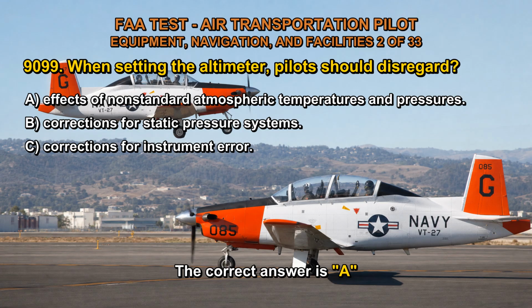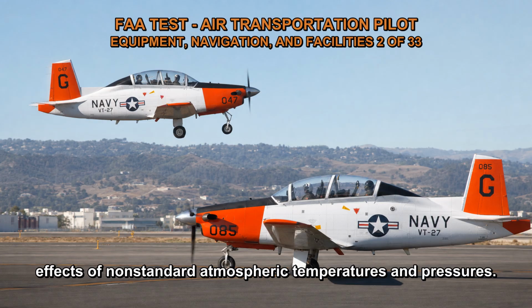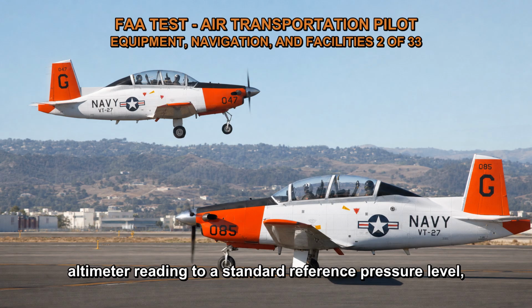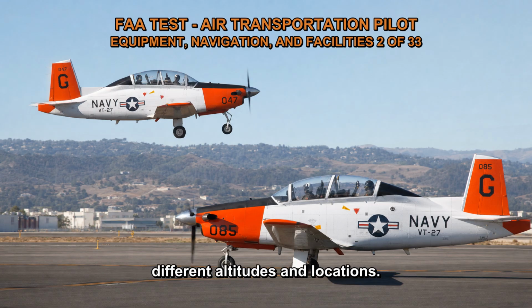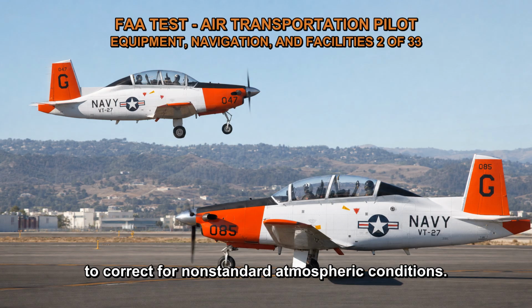The correct answer is A. When setting the altimeter, pilots should disregard the effects of non-standard atmospheric temperatures and pressures. The altimeter setting is used to adjust the altimeter reading to a standard reference pressure level, typically sea level pressure. It is not intended to account for variations in temperature and pressure that can occur at different altitudes and locations. Pilots should focus on setting the altimeter based on the provided altimeter setting, rather than attempting to correct for non-standard atmospheric conditions.